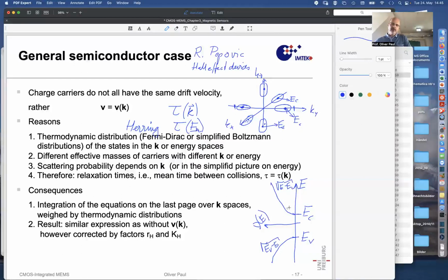And then the Fermi function lets these available states, whose number is specified by D of E, be occupied in a way that dies out exponentially, like this. So for instance, I'm drawing here a clearly n-doped sample with more n's than p's, so more electrons than holes, and each of those electrons has a tau that depends on the energy, on that energy scale.